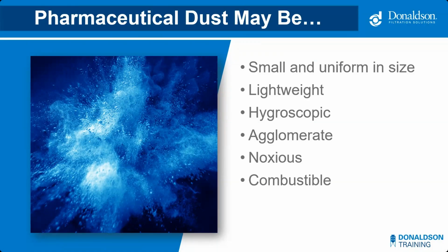Agglomerative dust is a dust that tends to stick together, either as a nuisance dust or part of a process. Dust that's introduced to moisture or solvents commonly will attract or bind to other small particles, which creates large clumps. It can create filtration issues unless planned for in advance. Prolonged exposure to many varieties of pharmaceutical dust can definitely be hazardous to workers' health and environmental health, and it's typically combustible.